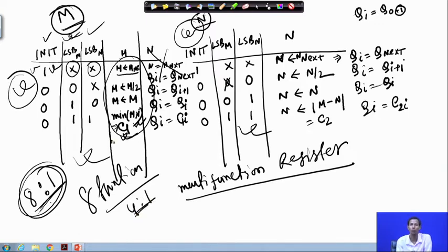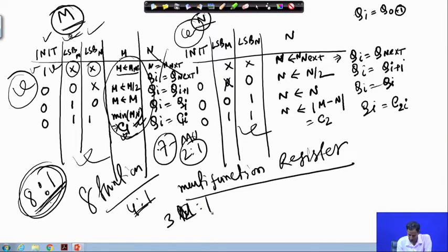So, that means I need one multiplexer where I will use these 3 control signals, but I will implement only this particular function. So, an 8:1 multiplexer means what? I need 7 2:1 multiplexers for implementing this 8:1 multiplexer, right. But here I need to implement only 4 functions. So, using only 3 2:1 multiplexers, I can implement this function.